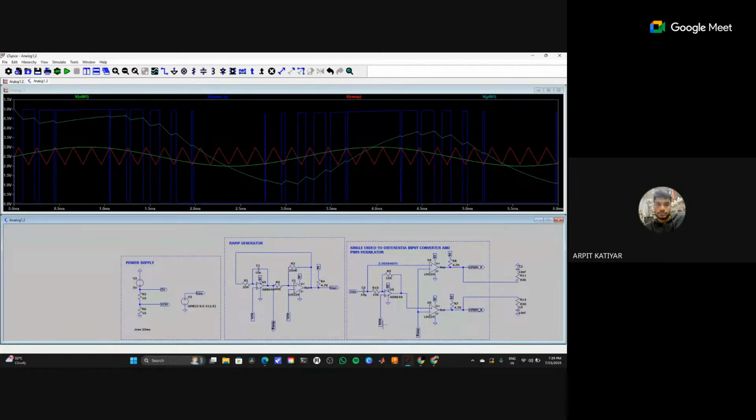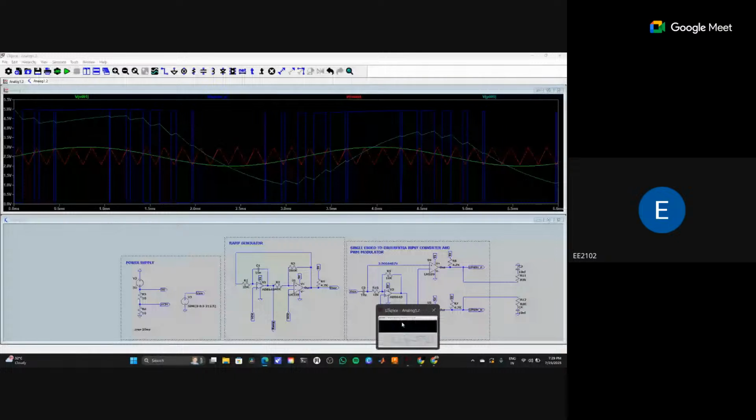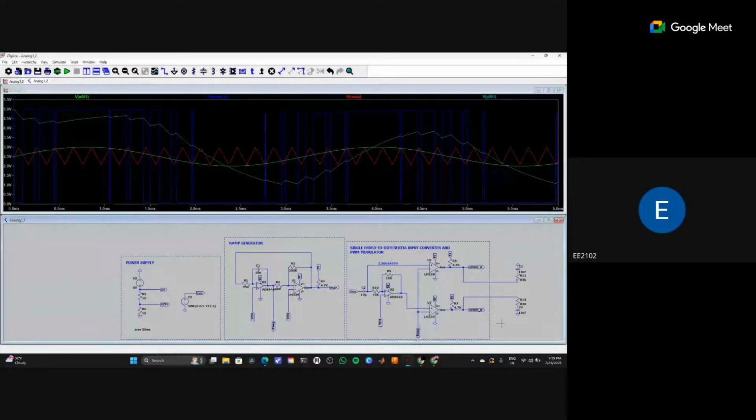Okay, so you were saying this one. Just change the cutoff frequency of the low pass filter. Either you can decrease or increase and just check the variation, so you can understand it better. The signal is not constructed properly because there are some noises when we convert the signal into PWM, so the signal will be distorted. For proper reconstruction, we have to choose the appropriate frequencies.